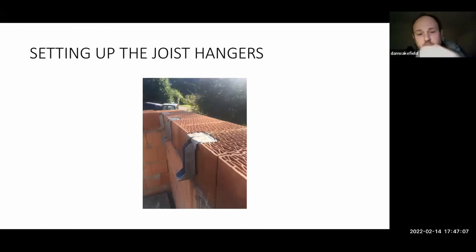What we did is knock up a little jig and use a wood router to rout a little pouch into the top of this course, and sat all our masonry hangers into that little slot. Then we could do our next course over the top without them interfering, and that worked really nicely. The thing to watch is this air tightness junction, because you can't ever access that again.